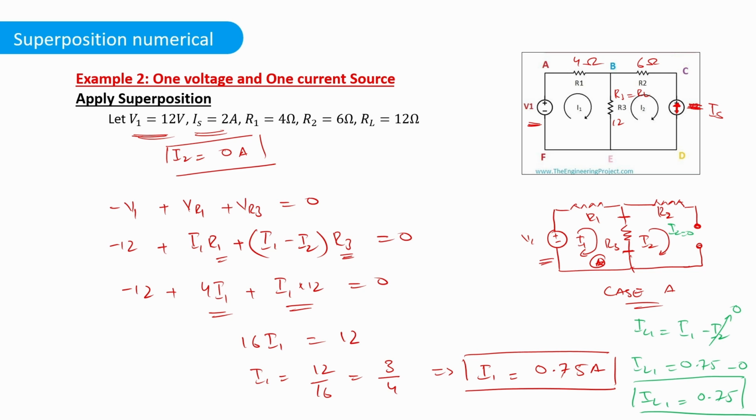Now what we will do is solve the circuit for the second source, and deal with the first source as a short circuit or open circuit. So let's do that in the next slide.